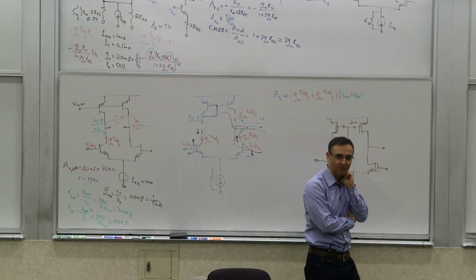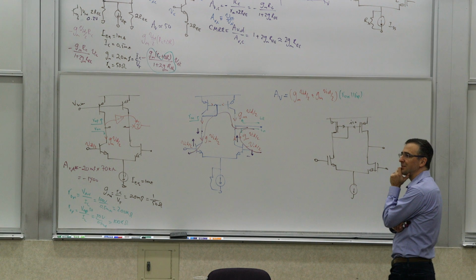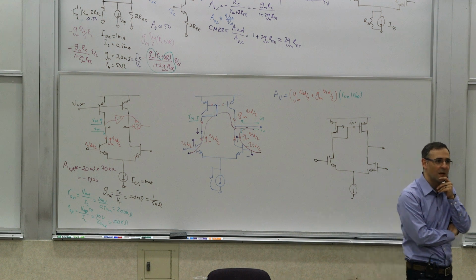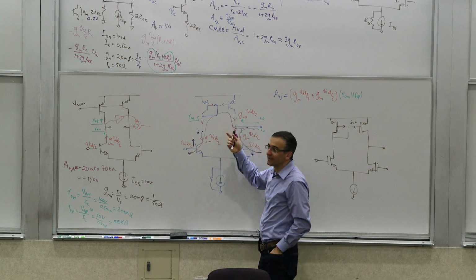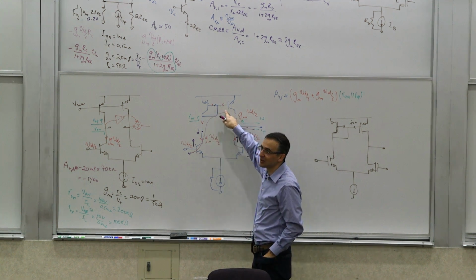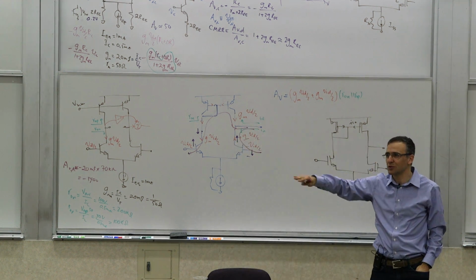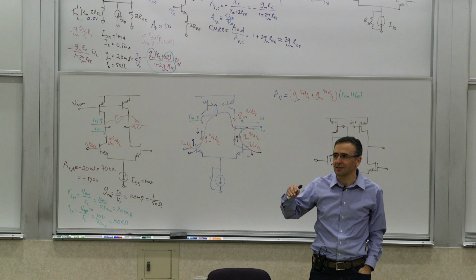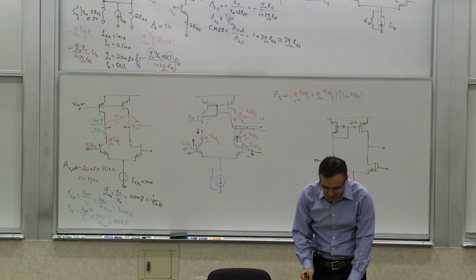When we talk about high frequency stuff, you will see that if you have systems where there are two pathways, and one of them is slower than the other one, it generates a pair of poles and zeros. We'll talk about that extensively, so if it doesn't make a whole lot of sense, don't worry about it. That is basically creating an extra pair of poles and zeros. For example, this pathway can start degrading before this pathway degrades, and therefore your frequency response will have a two-step behavior. That's characteristic of a pole-zero pair. And when you do that, you can have overshoots and undershoots and things of that sort happening. We'll talk about that extensively again when we get to it. But that's the essence of it.